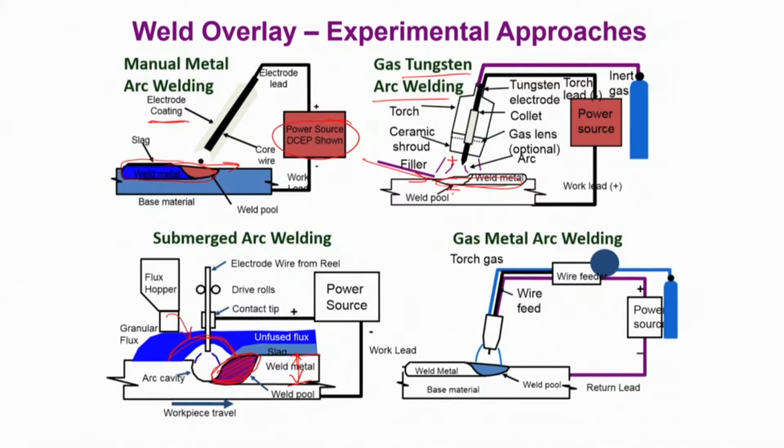The slag phase is molten, but you also have a solid crust on top of that. That means it is completely covering and protecting against the possibilities of external oxidation. The weld pool can be fairly deep, but most importantly it doesn't come in direct contact with air. So you have a much cleaner weld overlay with very little scope of trapping any bubbles, porosity, or even slag particles.